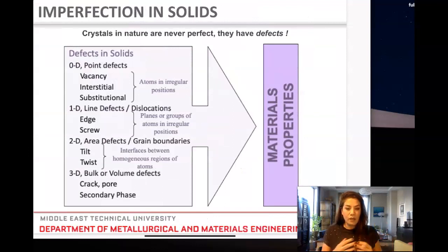All right, so what types of defects are out there and how can we characterize them? An easy way to characterize a defect is by dimension. There are going to be zero-dimensional, no-dimension defects. We're going to call them point defects. There will be one-dimensional, two-dimensional, and three-dimensional. The difference between them is the way we define the defect. For example, if I want to define a vector in space, of course, it is a line, so it's one dimension, and I have to address a length, right, and two initiation and endpoints to it.